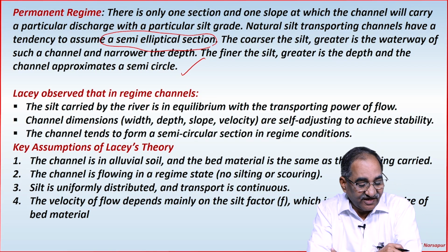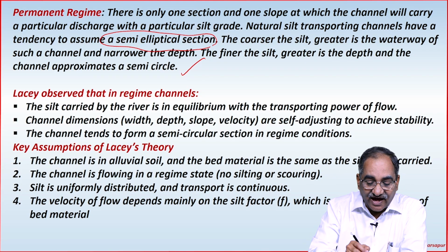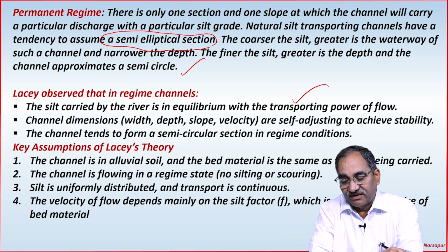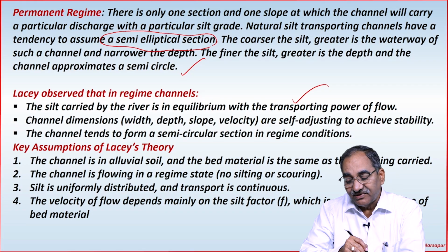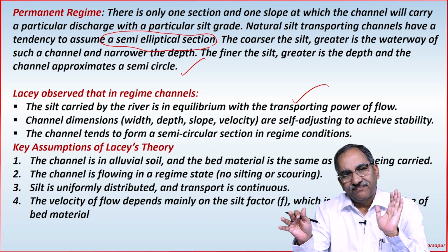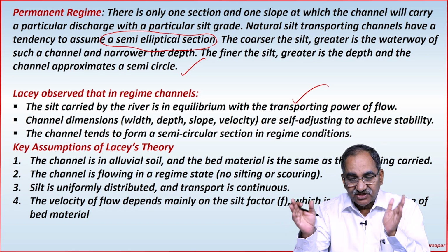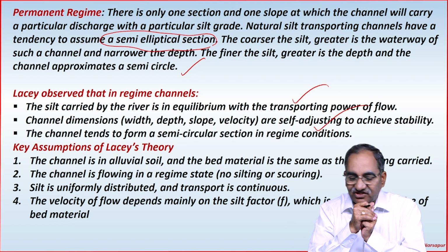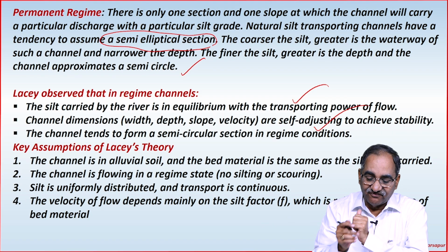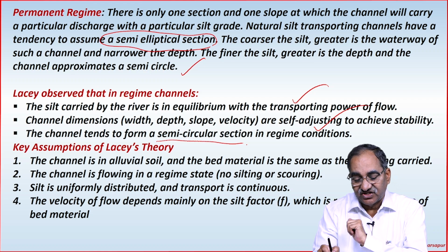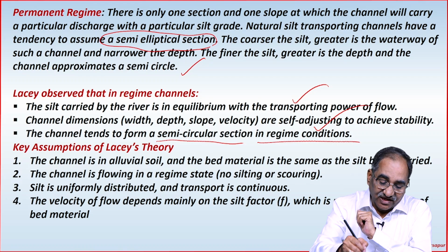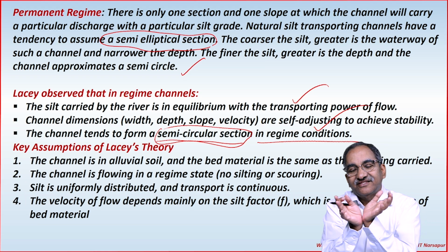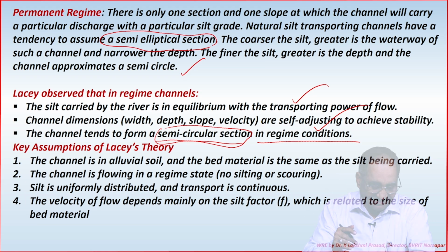Lacey observed that in regime channels, the silt carried by the river is in equilibrium with the transporting power of the flow. Channel dimensions are self-adjusting. The bed width, the depth, the slope and velocity are self-adjusting to achieve stability. The channel tends to form a semicircular section in the regime conditions. Semicircular, semi-elliptical, it depends on the section dimensions.